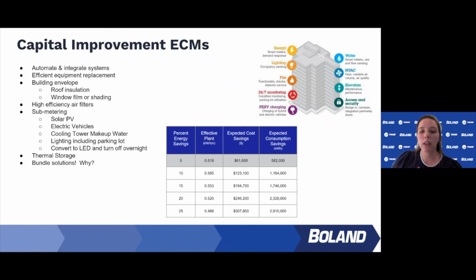If you tie all your systems into one, you'll be able to figure out what spaces might need air conditioning based on who's in the building. We also recommend equipment replacement for a more efficient system. If you have two big old gas boilers and you're running one in the summer, maybe you can change your boiler system so you have a few smaller boilers and you're not running this large boiler in the summer. These are larger projects that help you save money in the end.